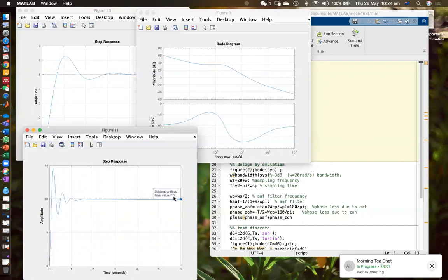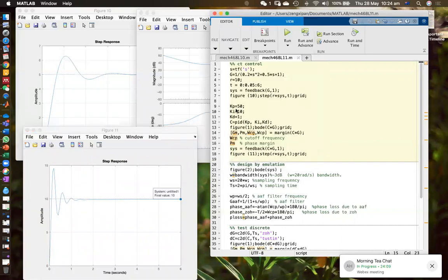So there's no error because we have this I there. Once you have I there, there's no steady state error because if any error is there, this component is going to add all those errors together, even a small error, they're going to accumulate to a bigger value and eventually become compensated. So that's what KI is for.